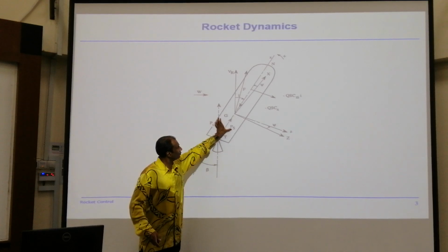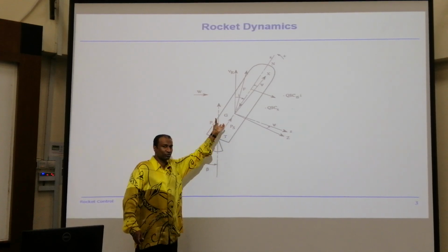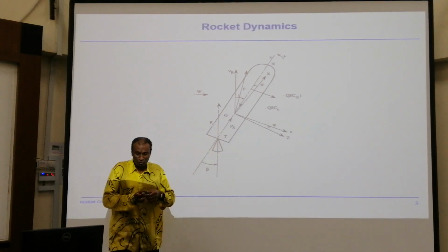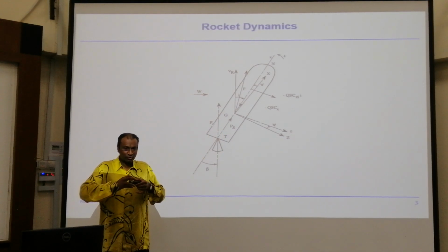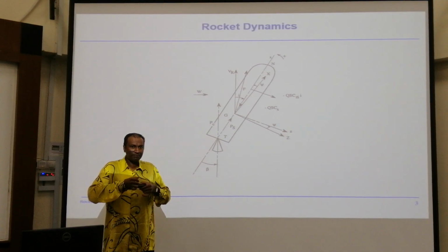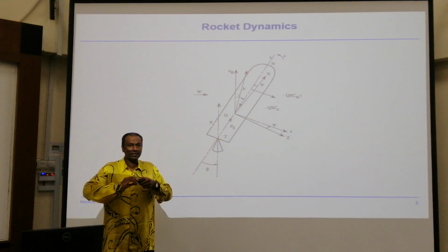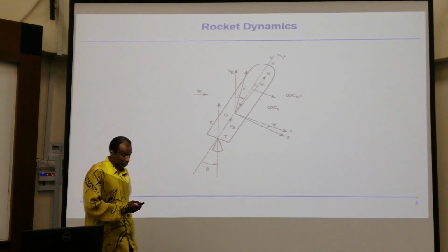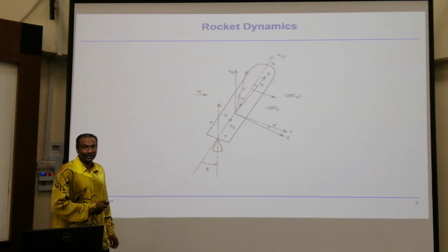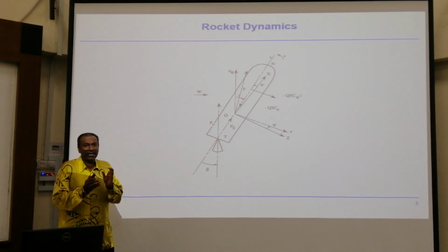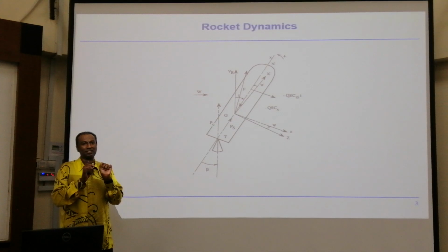if you want to correct the rotational motion along your x, assume this is x, you fire up and you fire down, and this will rotate. So any rotation you can induce by just not using this, you can't do that. This is only for translation motion. Any rotational motion you will see on launchers, in their body, they have all these small thrusters.